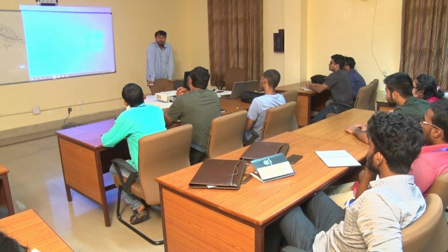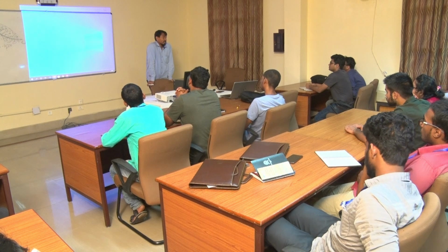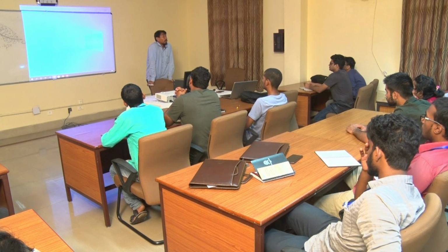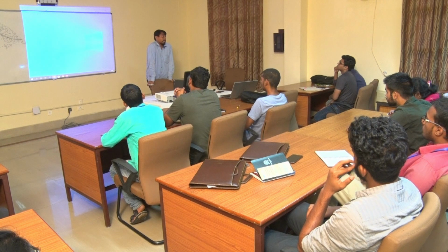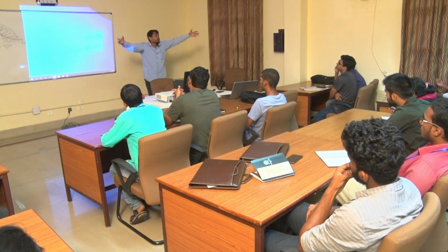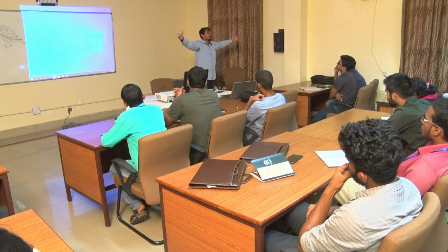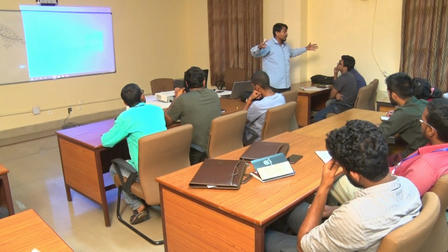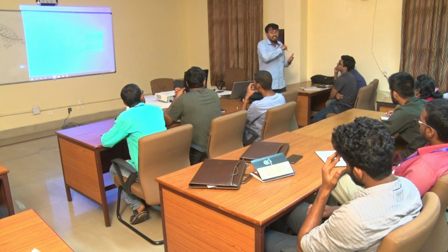In that university, they have the facility to test overburden dump material of any size. Their sample size is 1 meter radius. They have developed a triaxial test setup of 1 meter radius. The laboratory is a big room, a factory-type room, required to test a material of 1 meter radius in triaxial, because there is no standard. They have developed their own standard and they are working very well. Why is it required?